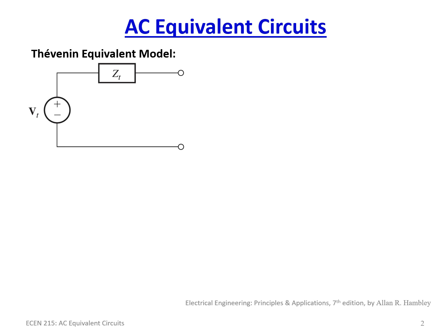So previously we had DC equivalent circuits when we were going over purely resistive elements and looking at DC circuit analysis. The models, the Thevenin equivalent and also the Norton equivalent that we'll discuss in a moment, nothing really has changed in the sense of the concept behind it. Of course, the thing that's changed now is we have brought in the concept of AC phasors and AC power supplies. So we have a frequency component. We have actual impedances now instead of resistances. So it's just the mathematics has changed, but the overall model has stayed the same.